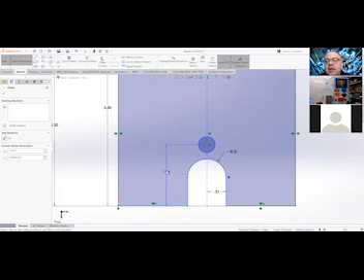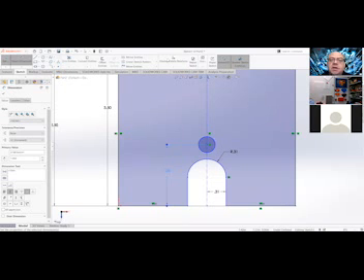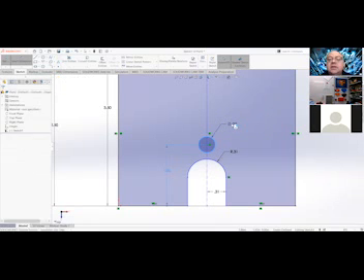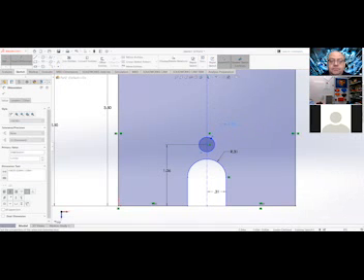That's exactly right. It looks right, but when I place it, it's actually being rounded. I'm pretty close, not exact. So never trust yourself. So 1.06, make it exactly right. Then still in the Smart Dimension mode, I'm going to pick the circle, and it knows that a circle is a diameter. So I put in decimal 2 point, oops, got to place it first, and then 0.255, enter, and I can now turn off my Smart Dimensions.